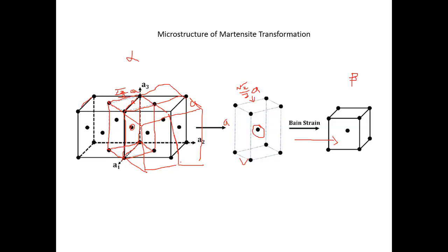So before I reach this slide, the question is that we need to find out a possible pathway for the transformation from FCC structure to BCC structure to occur. And after discussing this slide, I think we now can clearly see a pathway for that to occur, right? Because we already can see there's a BCC-like box in the FCC structure. Now what we need to do is simply to deform this box, to make it more cubic and convert it from the cuboid to a cube, and then we can actually have the BCC structure.